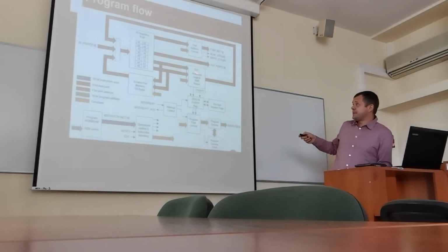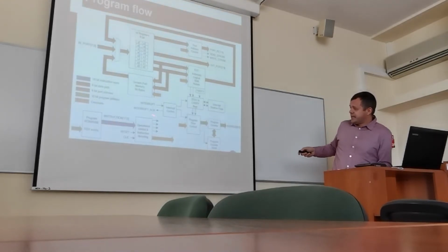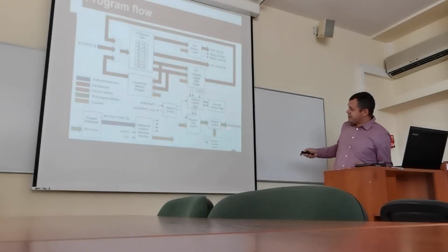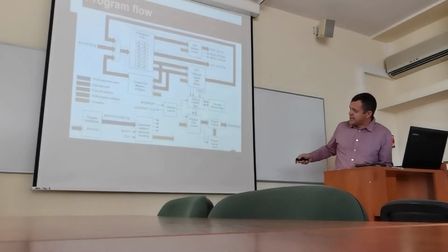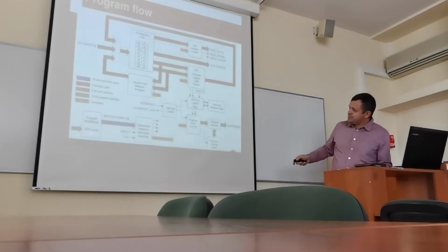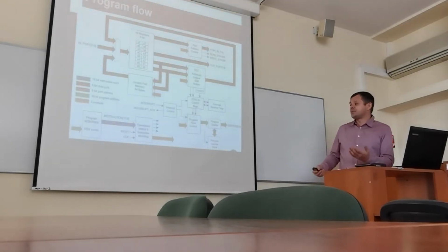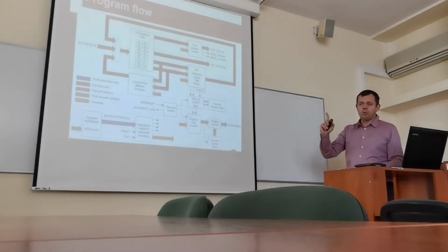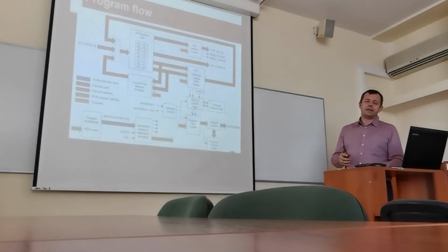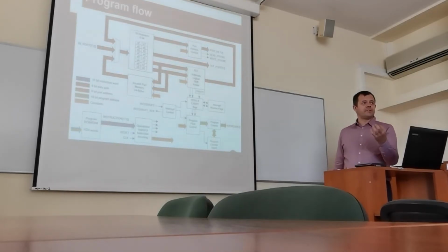Take a look. We've got the arithmetic logic unit, which is controlled by the instruction decoder, which fetches the program from the program memory. There is a program counter pointing to this program memory. The program counter is 10-bit, which means it is possible to address 1024 words, but mind that, words, not bytes. Again, be careful here.